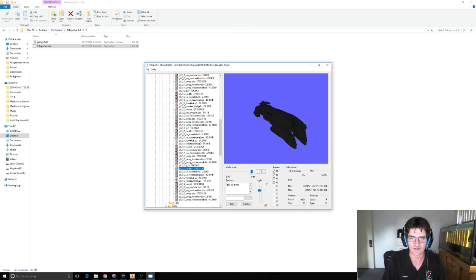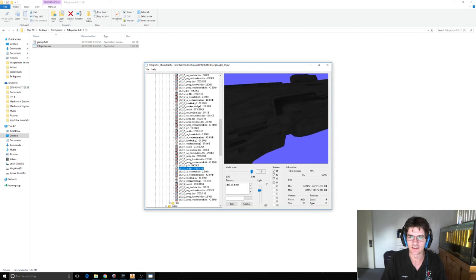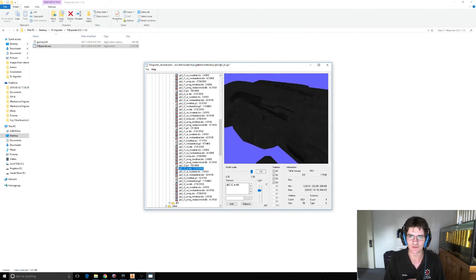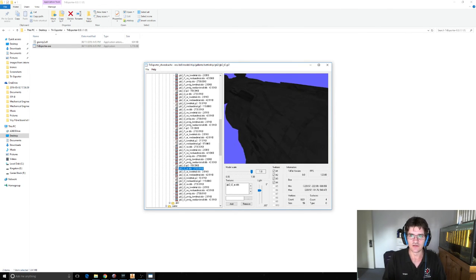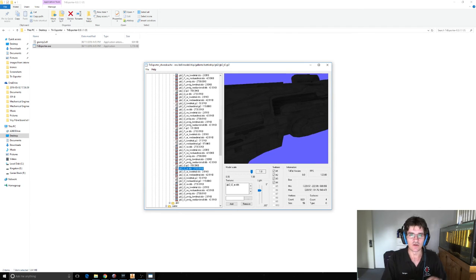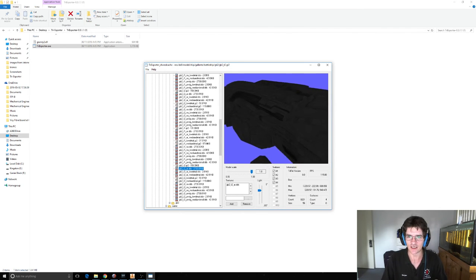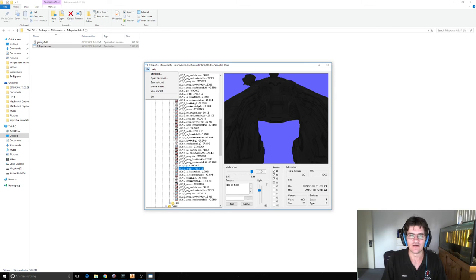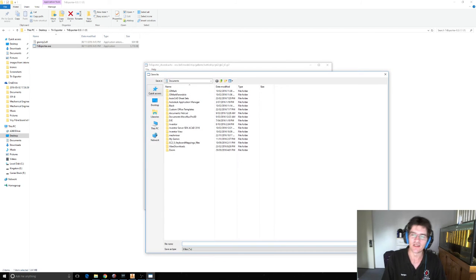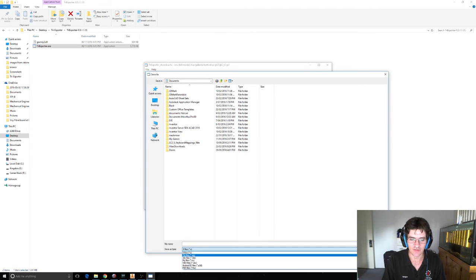So we'll grab this one, and as you can see, it's actually put in all of the model textures themselves. No colors per se, but it does have all of the skin textures, like where the hull changes are and the cutaways for the lighting, etc. Once you've got what you want there, you go up in here to File, and then you go Export Model. Now, for operation with Meshmixer, you're better off using a OBJ, otherwise known as an object file.